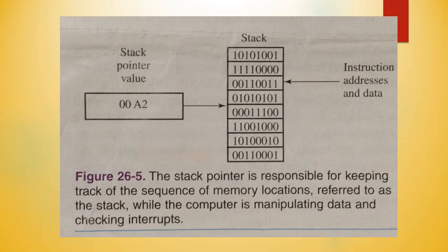If a program has not been completed or repeated as a loop within a certain amount of time, the watchdog timer issues a reset command. A system reset sets all of the register values to 0. The reset feature allows the controller to recover from the crash. It releases the program and sets the controller to start over again.